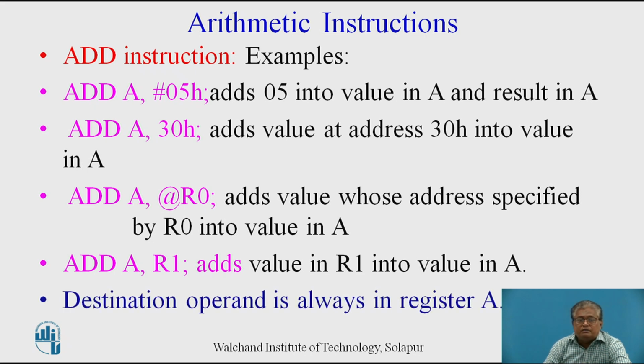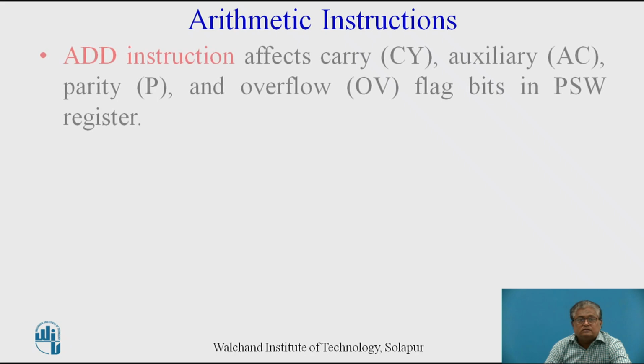Destination operand must always be register A. ADD instruction affects the carry flag, auxiliary carry flag, parity flag and overflow flag from the PSW register.